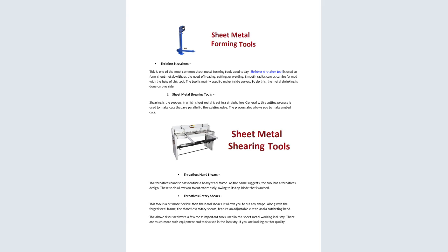So we have types of shearing. We have throatless handle shears. These throatless handle shears feature a heavy steel frame. As the name suggests, the tool has a throatless design. These tools allow you to cut effortlessly, meaning you don't need a lot of force to be able to do the cutting of the sheet metal.